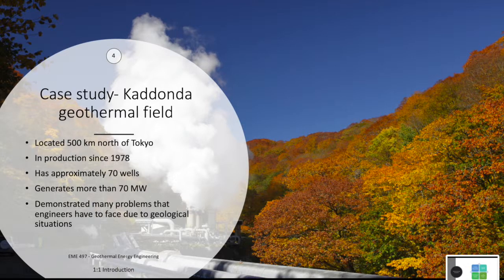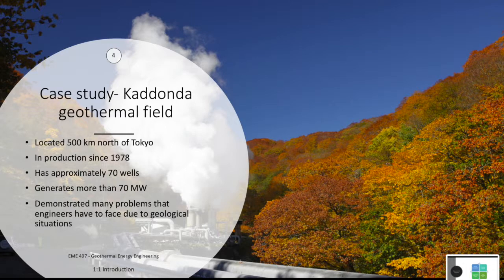At a depth of 3,350 meters, excess CO2 was discovered in the drilling fluid. Drilling fluid is really good because it can show what's going on down the well when it's brought back up, and you can also treat what's going on down the well. So to combat the CO2, lime was added to the drilling fluid, which then turned the CO2 into calcium carbonate. This was a successful effort to mitigate issues within the well.